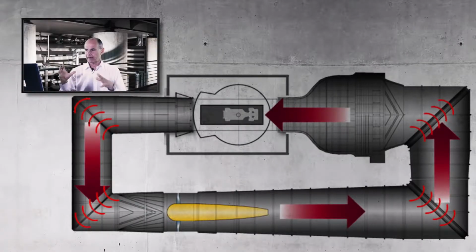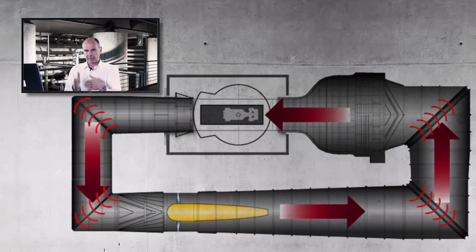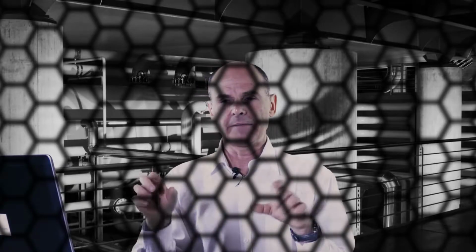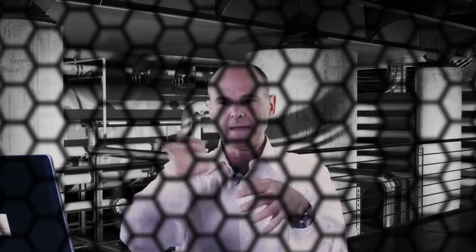When we get round to the last leg before we have the working section, we have what is called a settling chamber, and as the air passes into the settling chamber we expand it reasonably quickly. We then have a blockage caused by, in some wind tunnels it's the radiator, but we have a radiator and then separated from that a honeycomb, and the honeycomb is aligned so that you just see the edge of the material in the direction of airflow, but any remaining swirl in the air is almost entirely eliminated by passing through a rather long series of effectively rather long thin tubes, so that the air, if it's swirling approaching the working section, that swirl is eliminated. So that's the purpose of having a honeycomb.